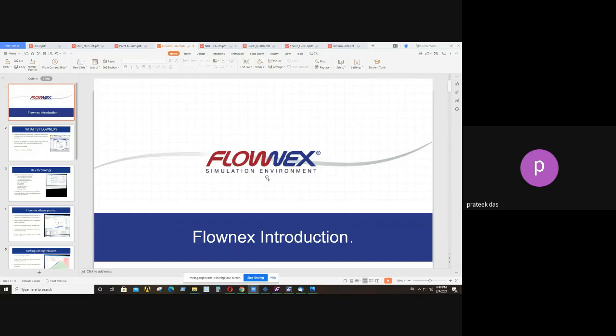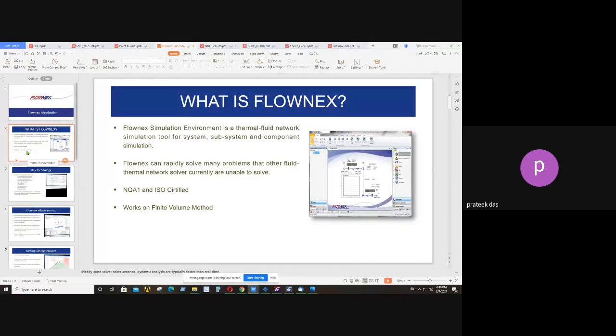In this method, the solver will first guess the initial pressure, and after guessing the initial pressure, it tries to solve the mass, momentum, and energy equations. When these equations are solved for that particular pressure, it then checks energy conservation. Let's say it is not conserved, then the solver will change the pressure, and for that new pressure value, it again tries to solve those equations. So this process is iterative, and it will continue until we get the solution.